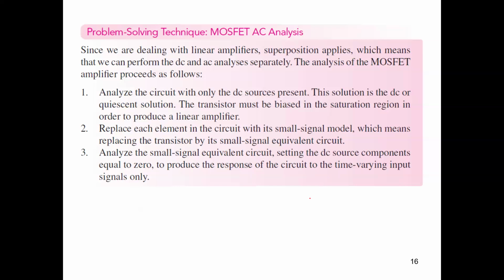So these are the steps now, guys. Start firstly with the DC, then calculate the AC parameters that we have, the transconductance and the output resistance, and substitute in the relation that we provided from the AC analysis. So this is a complete analysis for the common source amplifier.